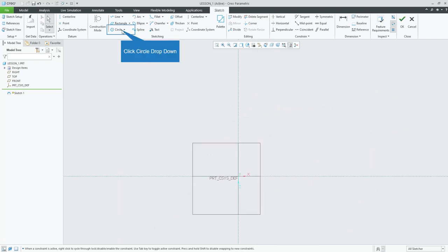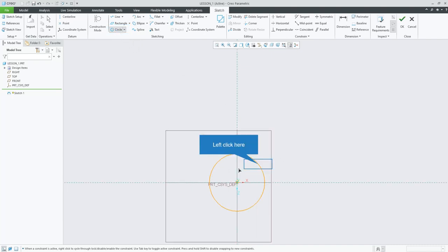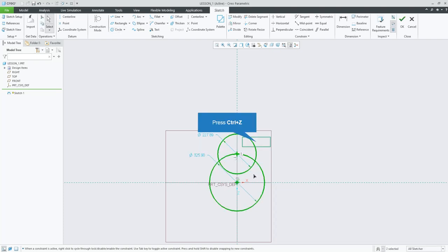So now circles. The center, what's it called? Center and point is probably the most useful circle. Kind of like the center rectangle. Click the center point, allow your mouse to move, and you can move out to create the diameter. Click again to create the circle. So click center point, drag your mouse without holding click, click again to complete the circle.